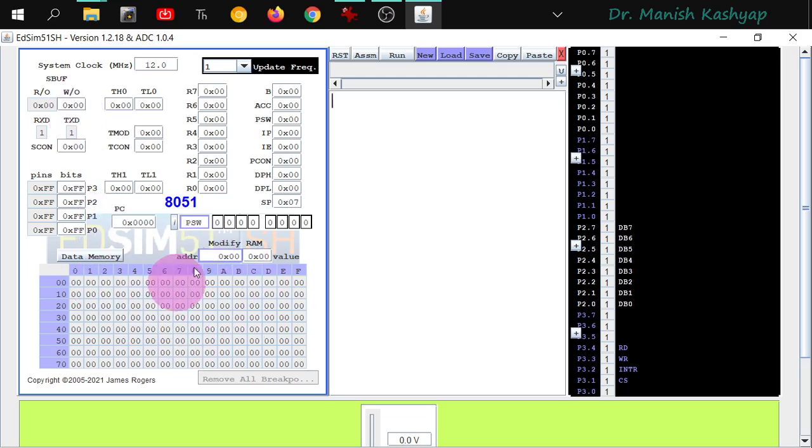And this is the RAM structure. You can see that it begins from 00 and it ends at 7FH, right? So the last location is 7 and F. So 7FH will mean 127. It starts from 0 and ends at 127. That simply means that you have got 128 bits. Sorry, 128 bytes, not bits. Every location that you see here is a byte, and the double zero actually represents two hexadecimal zeros, as was the case with 8086 and 8085 also, right?